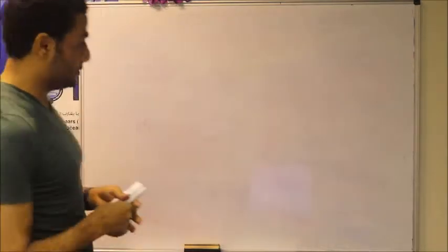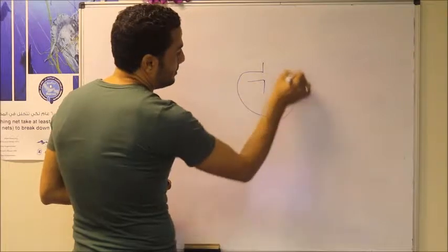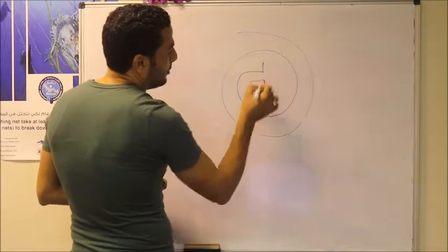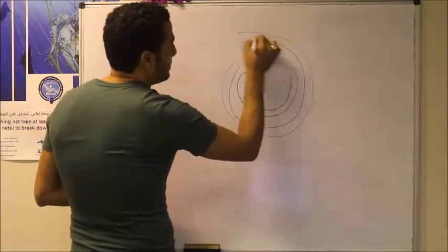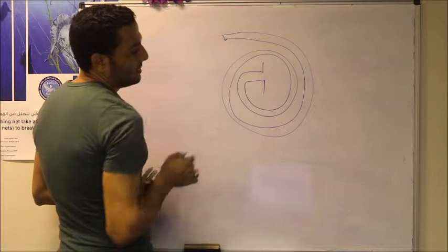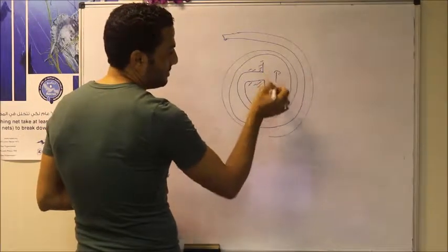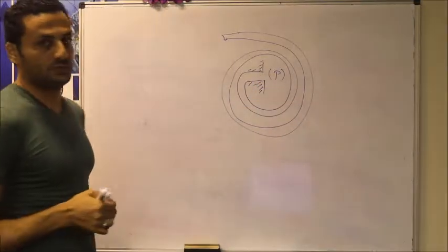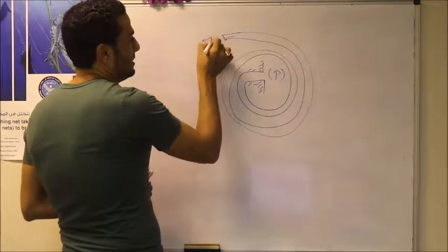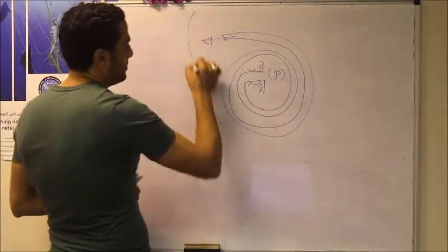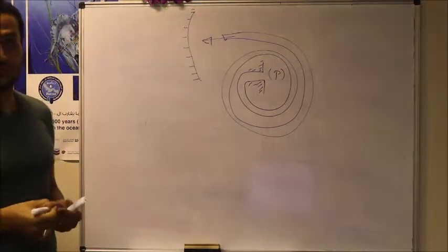The idea of the Bourdon tube, let's consider the helical shape, is that we do have a tube with two ends. One end is fixed, and the other end is free to move. This fixed open end is subjected to the pressure that we want to measure. The free end is a closed end, and this is connected to a pointer, which is connected to a scale that is calibrated to give the reading of the pressure.